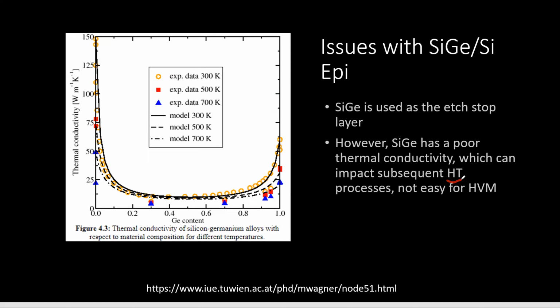For the CVD process, imagine for HDP, you want to take the tool to 1,000 degrees to get your HDP, high density plasma, to work. You have to use very high temperature. And when you do that, you need to cool the wafer with helium.